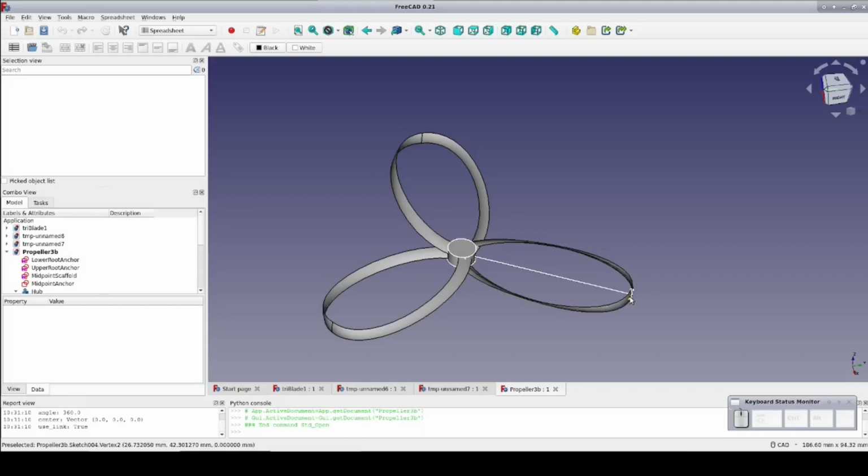Since as we move outward, the linear speed of the blade increases, we might prefer the pitch to get more shallow. We can't carry this to the final extreme, because a fundamental of the design is that we must turn up towards a 90-degree angle at the tip in order to loop around. However, we don't have to do that turn uniformly throughout the length of the blade.